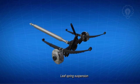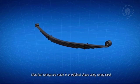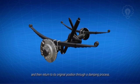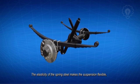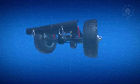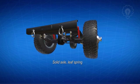The leaf spring suspension. How the leaf spring works. Most leaf springs are made in an elliptical shape using spring steel, which has the properties of allowing it to bend when pressure is applied at both ends, and then return to its original position through a damping process. The elasticity of the spring steel makes the suspension flexible, which can provide comfort and control when the car is driving. For decades, the leaf spring has proven to be a viable suspension system. It is common for many cars to use leaf springs as a dependent rear suspension.